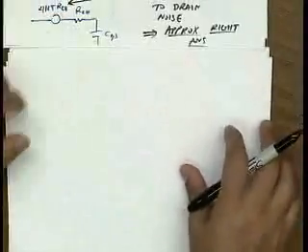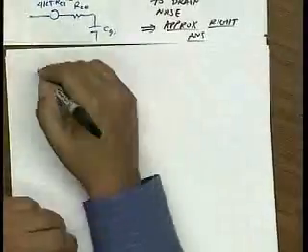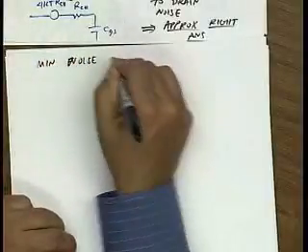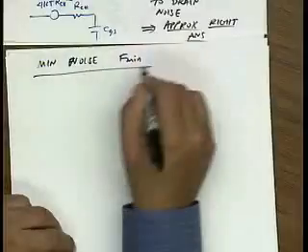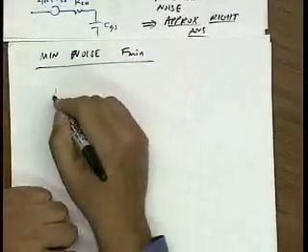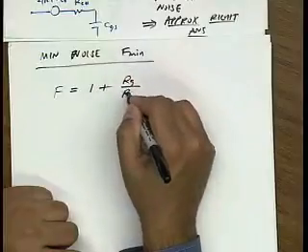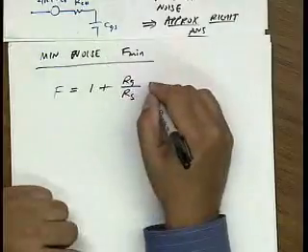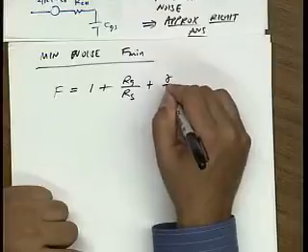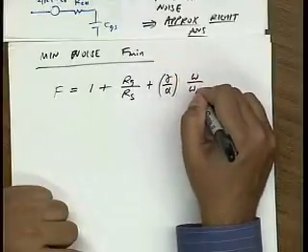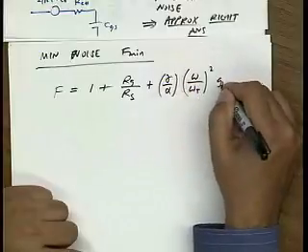And in particular, we'd like to find now the minimum achievable noise. And instead of using the two-port theory that we did last lecture, I'm going to do exactly what one of you guys suggested a few lectures back. In fact, it was Amin who said, why not just find the noise figure and then take the derivative with respect to source resistance.